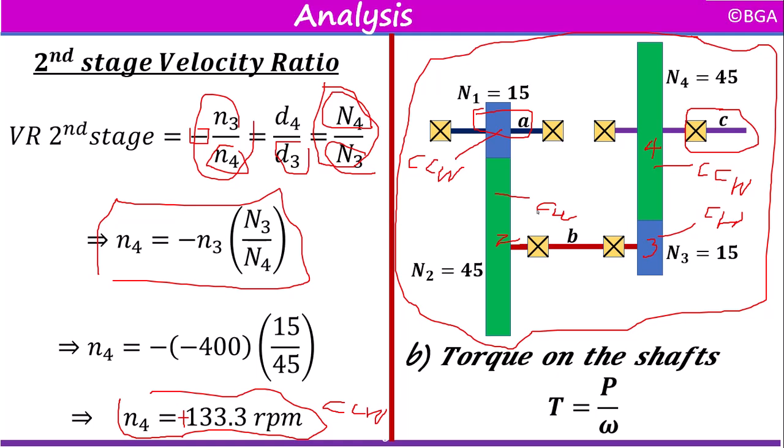You can see this clearly on this diagram. Input shaft A is collinear with output shaft C. Why does this happen? Because we used identical gears on each stage. Identical gears means, don't forget, gears that have the same gear teeth size. That means the diametral pitch for every gear here is the same.